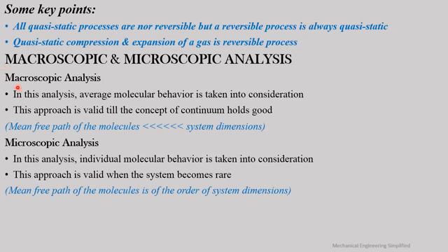Macroscopic analysis. In this analysis, average molecular behavior is taken into consideration. We will not take the individual molecular behavior; we will consider the average molecular behavior, how the molecules are behaving on a whole, on an average basis. That is our main concern in macroscopic analysis. This approach is valid as long as the concept of continuum holds good. What is that? The mean free path of the molecules is very much less than the system dimensions.